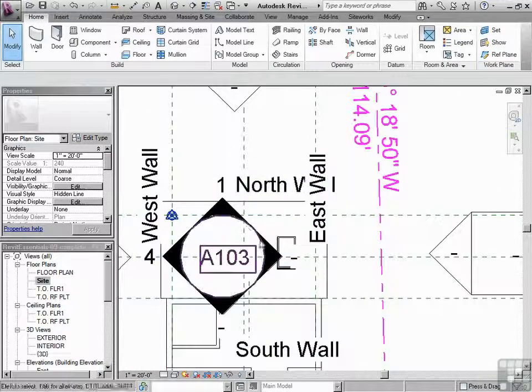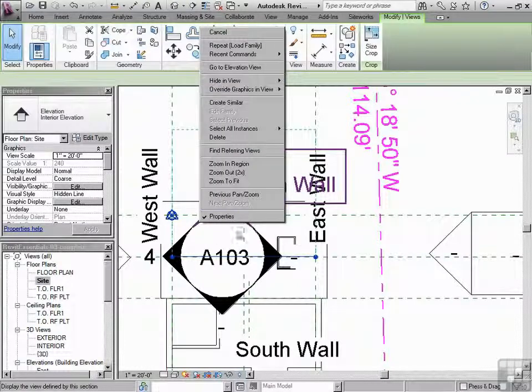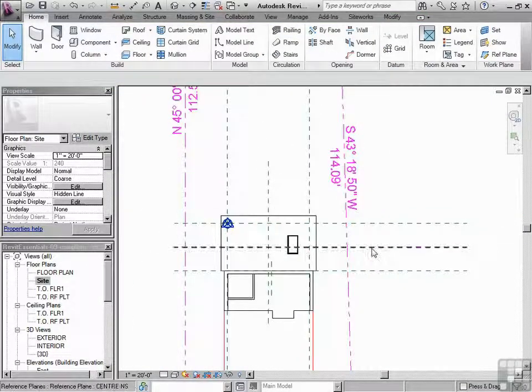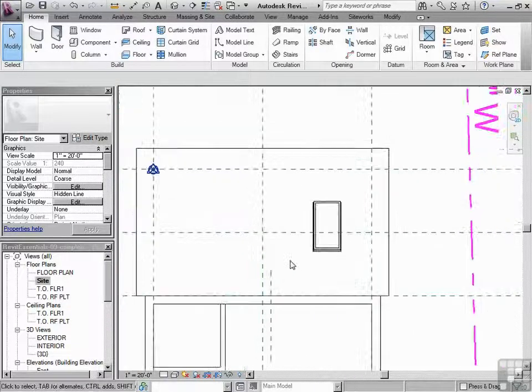Now, this is definitely in our way. We want to turn that off. Let's just right-click on that object. Let's go to Hide in View, and then Category. There we go. So now all of our elevation markers have been hidden, and it gives us a nice, clean look. Now, we have to do a little bit of math in order to balance these out. There are some Revit tools in order to lay things out, balance things out, and center things. But what we find is just using standard math that you would have to do, you're going to have to use standard math occasionally anyway. So let's take a look at how this might be done here.